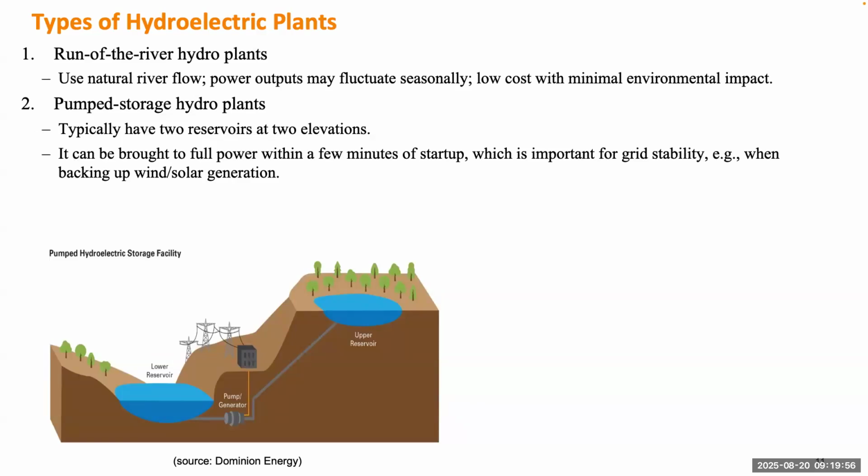It can operate as a generator if the rotor is leading the electromagnetic field, which means a mechanical torque drives the rotor to rotate ahead of the electromagnetic field. So it will generate electricity.